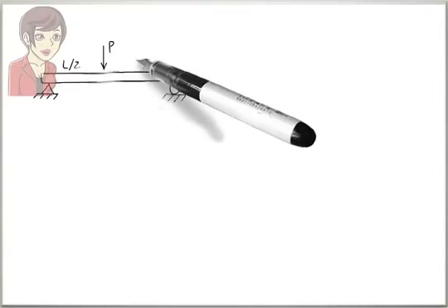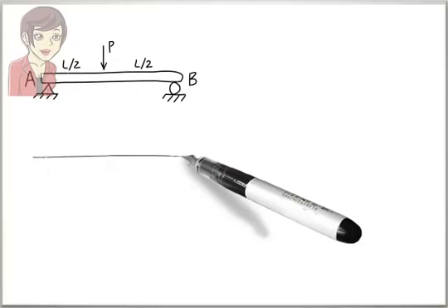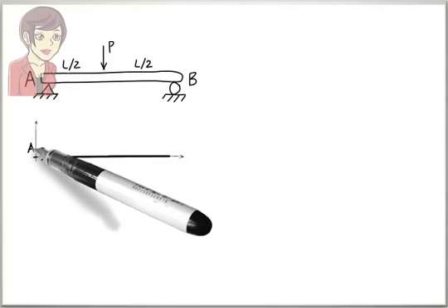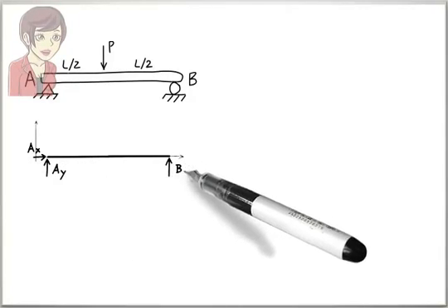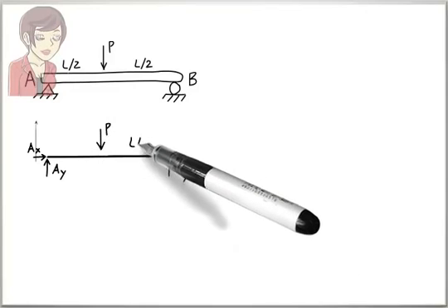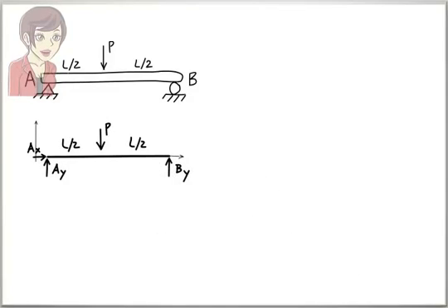In order to analyze a beam, it is customary to draw a diagram called the free body diagram, showing the applied and reaction forces and their locations in a Cartesian coordinate system. Note how each unknown force in the diagram has been uniquely labeled. The free body diagram helps with the correct formulation of the equilibrium equations. To determine the support reactions, that is, to analyze the beam, we use three equations.